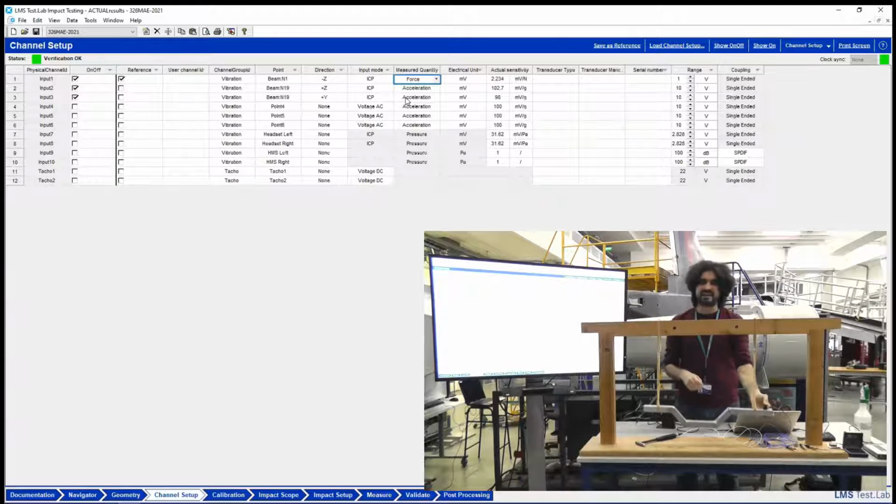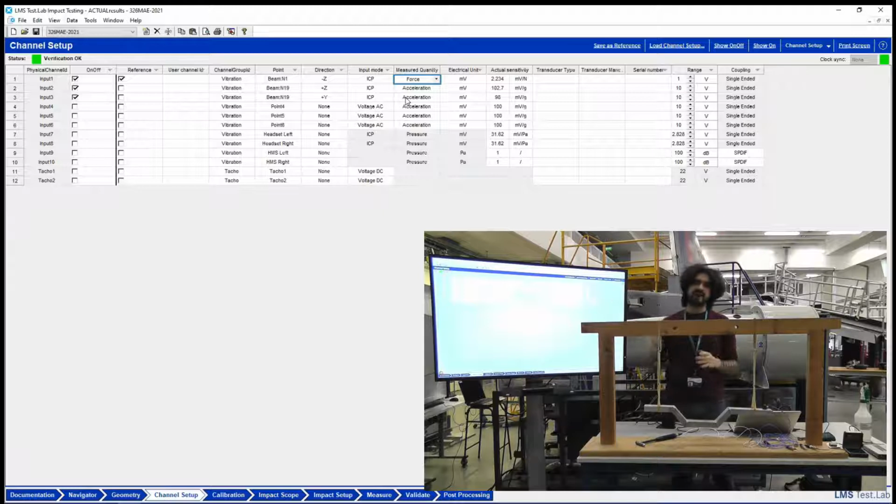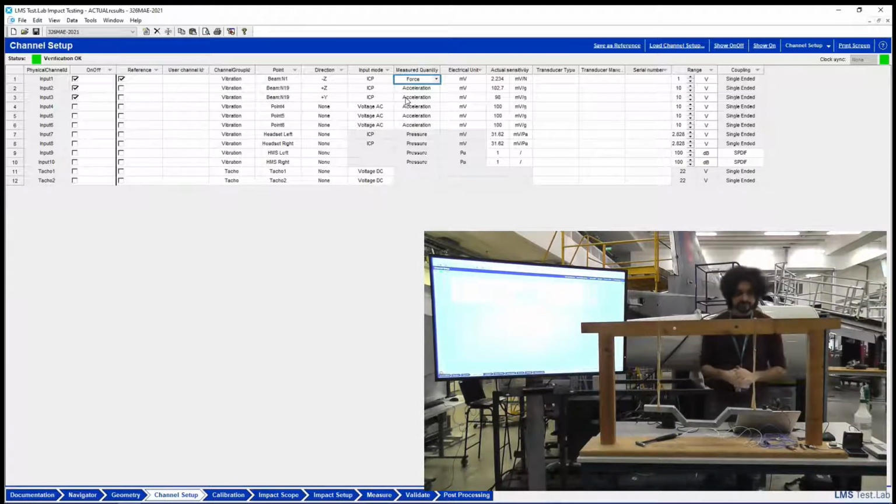So that means I can get rid of the x-axis channel, the longitudinal axis along the beam, because those vibrations will occur at very, very high frequency, and I don't care about those. You generally want the lowest frequencies, because those are the most important ones that carry the largest amplitude and also are generally in the operational range of your structure.